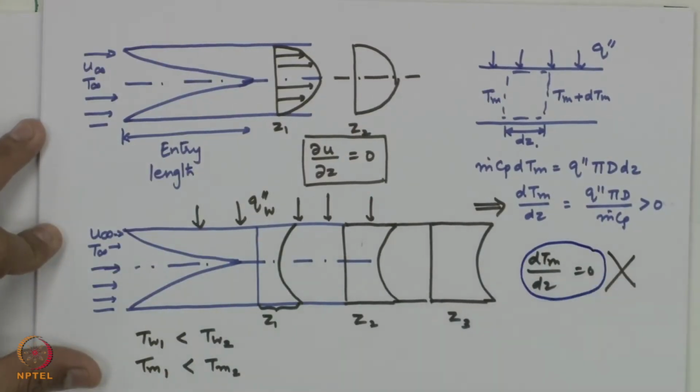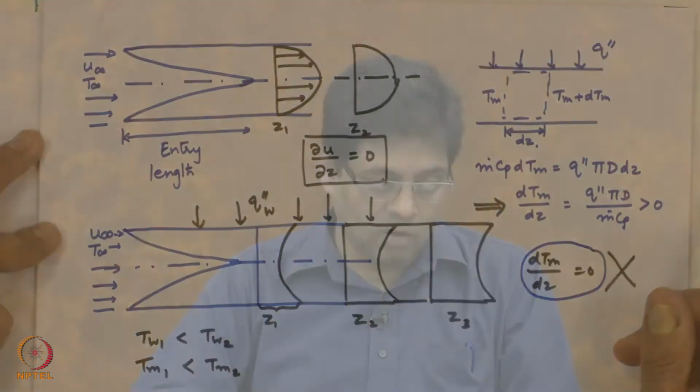That is not the definition of thermally fully developed. We would have an alternative definition, we will see later on. This is a very important distinction between the heat transfer aspect and the hydrodynamic aspect.